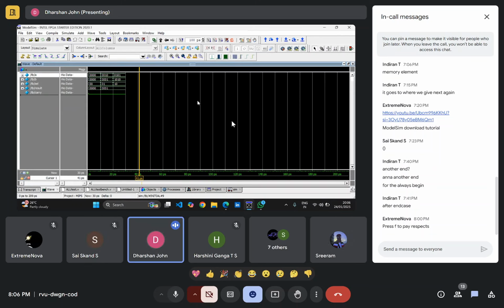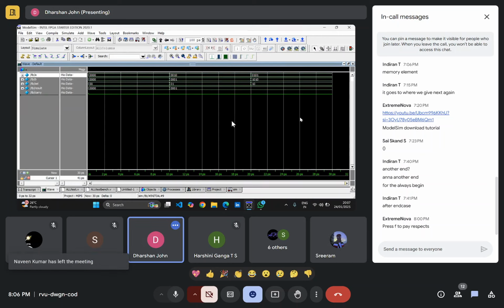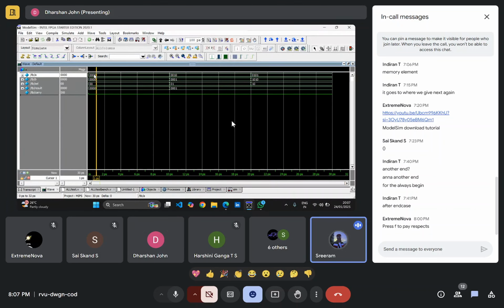What do I have to do right now? The F alphabet, on the keyboard there's an F, right? Usually yes, it's just full screen. F. Okay, nice. Full screen is on. It automatically fits to the screen if you press F. Now you are able to see the values of the marked signals. You can press anywhere at any instant and it will show the values and messages. Yes, you can see the values change, right?